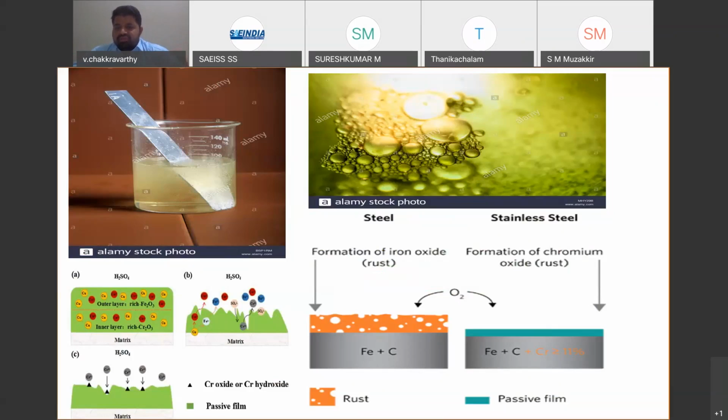There are a lot of solutions, like Ringer's solution, Kokubo solution, and different types of solutions. We can check in any type of simulated body fluid to evaluate the corrosion resistance and biocompatibility of the material. When the implant is immersed in the simulated body fluids, the metal will automatically start releasing some free electrons, which could be seen in terms of bubbles.